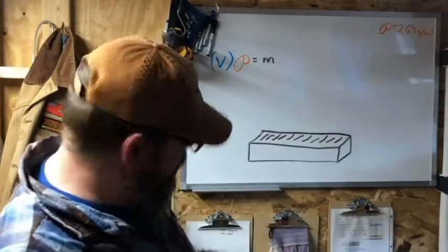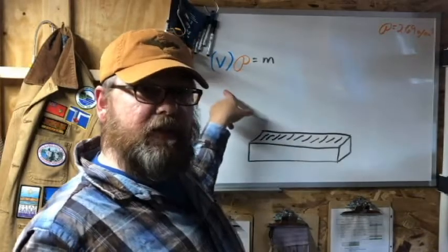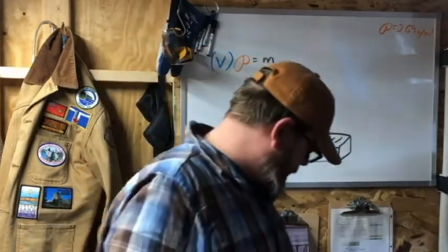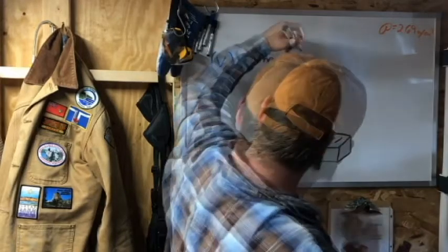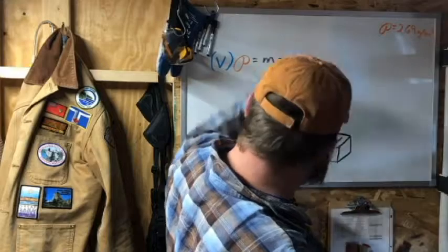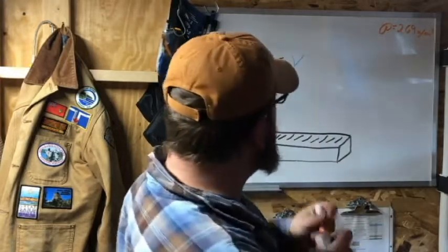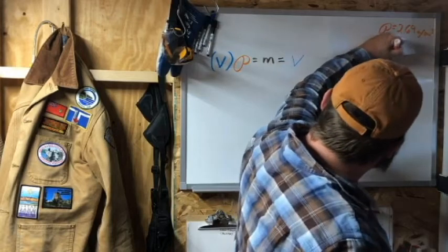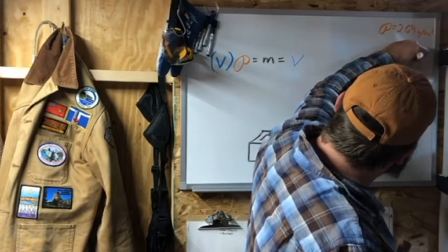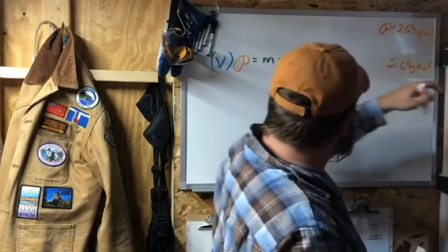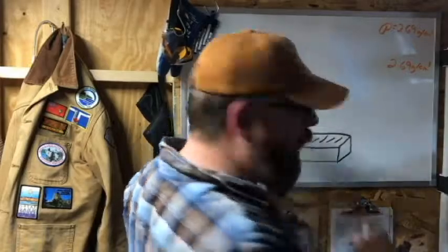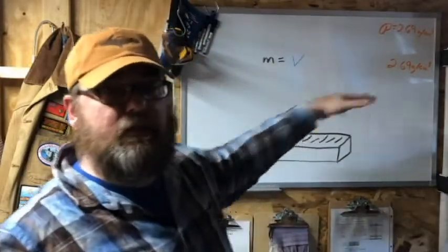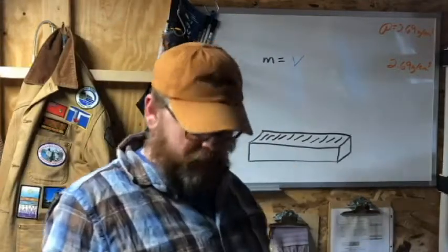So the equation we are going to use is going to look something like this. Now I'm going to flip this around so my mass is to the left. It's just a matter of doing this. You're not algebraically manipulating it, you're just repositioning for your purpose. So it'll actually be M is equal to my volume multiplied by my 2.69 grams per centimeter cubed. And there's a big space here for a reason. You'll see why in a second. So all we've done is move everything from the left to the right. That's just a language thing. It's not an actual algebraic manipulation.